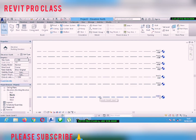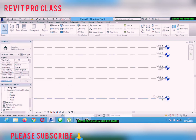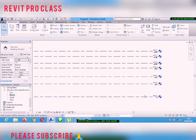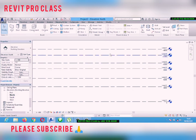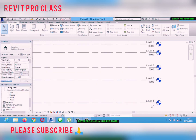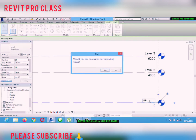This level 1 you see here is actually the natural ground level, and level 2 represents your foundation level, level 3 the height of your building, roofing parapet, then your roof and the top of your roof. So we're going to name them now. You double click on level 1, then you name it NGL, that is natural ground level. You click enter, you click yes.